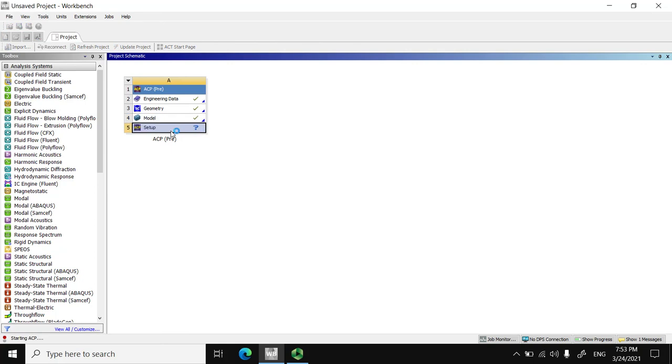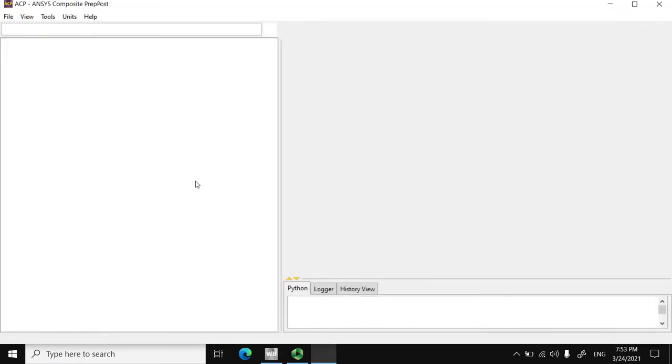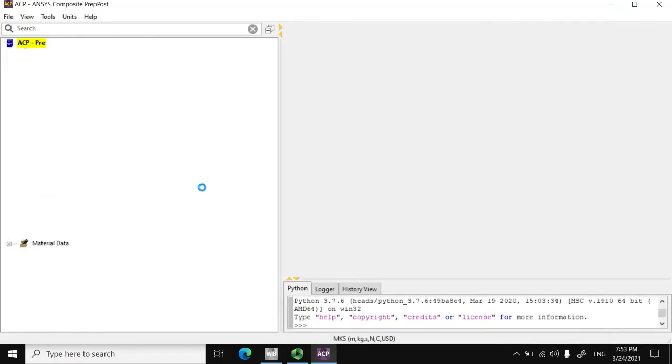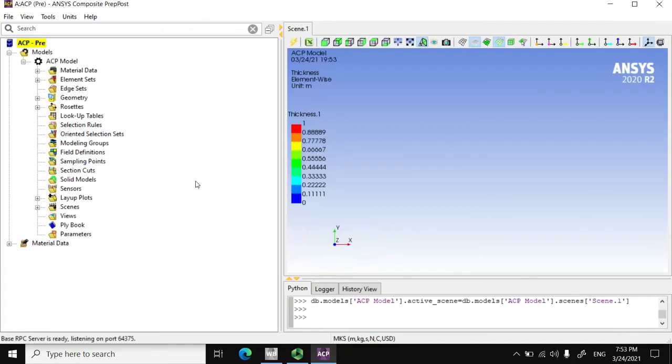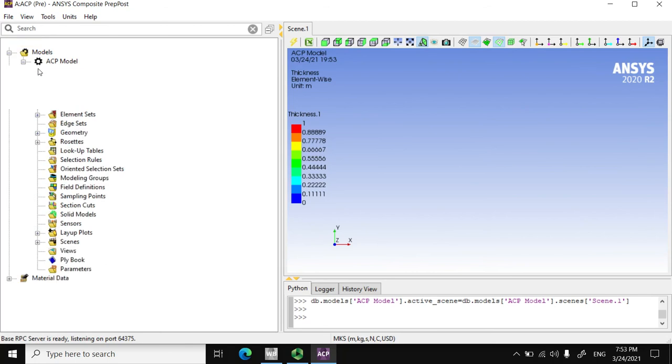So I go here now. On setup, I'm gonna set up the layup. I'm gonna do this 2 times. Once with a symmetric layup, and show you guys that when it is symmetric, you're not gonna see coupling between stretching and bending, but when we do unsymmetric, then we're gonna see that coupling.